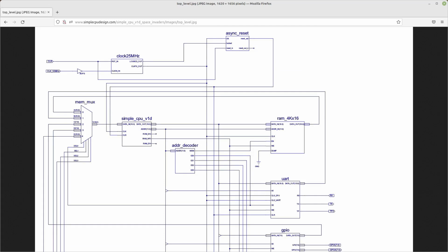The current plan is that the processor has a 4K memory space. Within that, I'm allocating 2K to system software, so subroutines that will support the various peripheral devices: the video controller, rotary controller, gamepad, etc. And that will leave 2K free for game logic. Now that may sound quite small, but remember that the tile data, the font data, is stored within a block of memory in the video memory, so that frees up quite a lot of space for the processor. And that video memory, again, can be configured by the user and effectively loaded into the bit file that is used to configure the FPGA. So you can add additional tiles and fonts to that video memory for particular games.